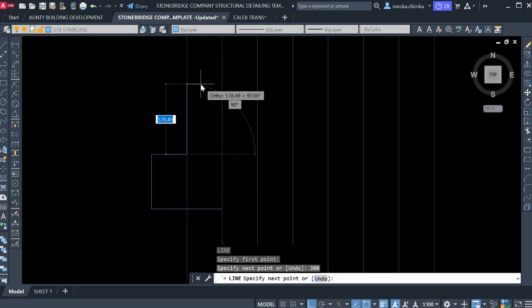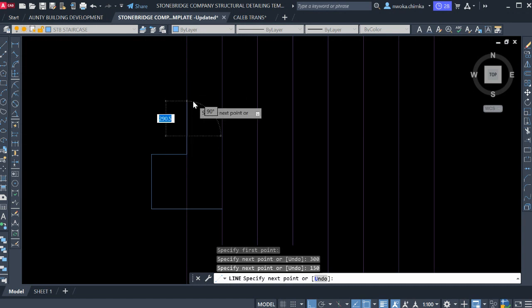So you either use 150, or you use 175, or you use 200. Don't try to mix your risers. You have to choose one riser and then be consistent with it. Okay, so we are using 150, which comes from the design. So I'll just type my 150 as my riser and type enter.